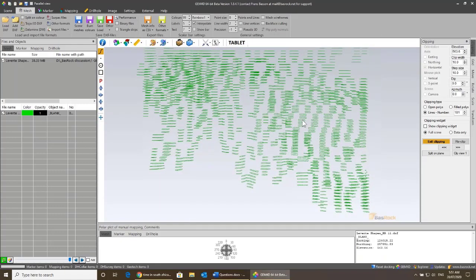So why did I choose 101 and not 100? You have to choose an odd number to get exactly the elevation that you selected. If you say 1, you get exactly that selected elevation. If you say 3, you get that elevation, and you get the offset distance up and down from that elevation. And I should have done that, and I haven't.